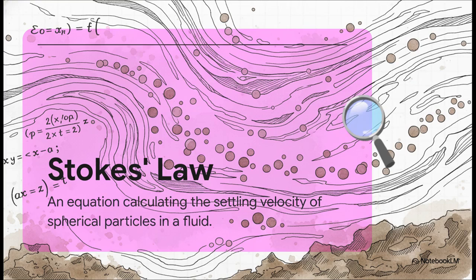And honestly, the irony here is just amazing. To figure out the size of microscopic mud particles, engineers have to bust out high-level fluid dynamics. They rely on Stokes' law. They have to assume the dirt particles are tiny little spheres, and then run complex equations that factor in the water's temperature, viscosity, and specific gravity. All of that math, literally just to quantify dirt sinking in a jar of water. It's this beautiful intersection of high-level physics and, well, literal mud.